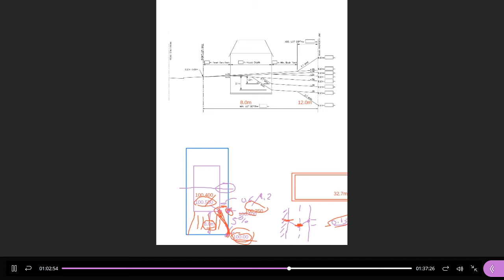If the difference between the front and the back were between the two numbers we just calculated, 2.56 and 0.98, right? Suppose the difference was 1.6. Suppose your existing ground was here, 1.6, somewhere in here. Then I would start at the back and come down at 3-to-1, right? Parallel to this. I would start at the front and come up at 3%, and I would find this solution. Then I would have this much extra usable backyard. Okay? And that's the way you would design it. I'll show you how to do that, right? You just have to understand that's what you need to do.